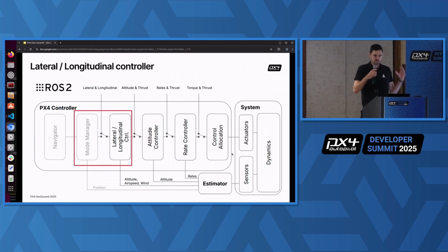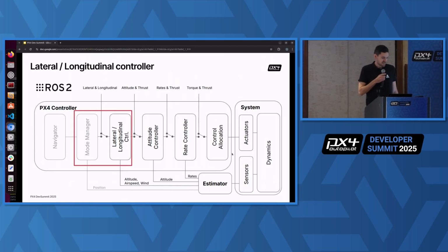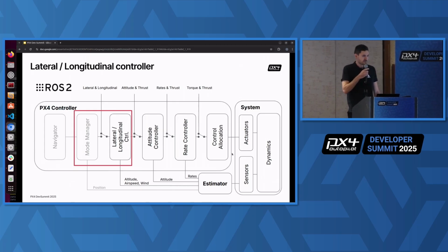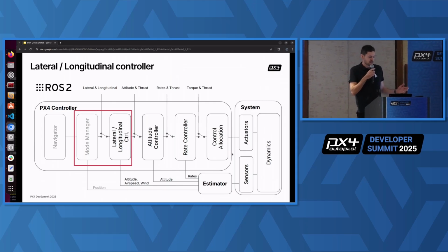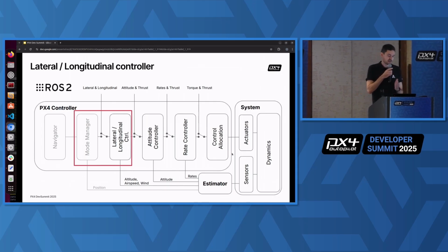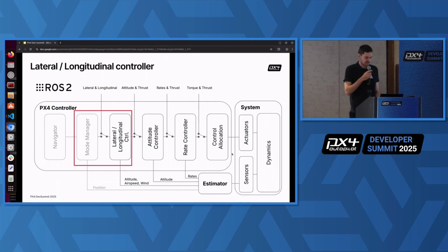Previously there was one big chunk of code that did everything, from setpoint generation to actual feedback control. Now it's cleanly set up into a mode manager that does the setpoint generation, and then a handler on the controller side.